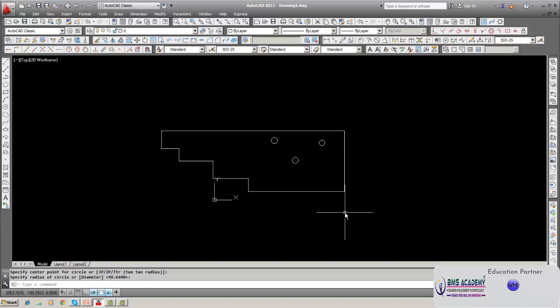So for that, what we do, you dimension from that reference datum in x and y coordinates, and then it is easier to feed the coordinates on the machine, and you can machine the component. That will be easier. If you put linear dimensions, every time you have to calculate the dimensions from one side.